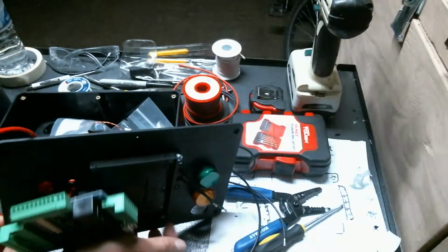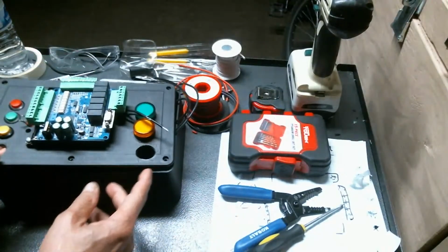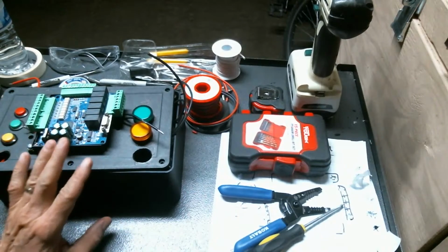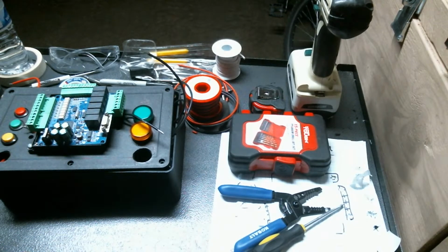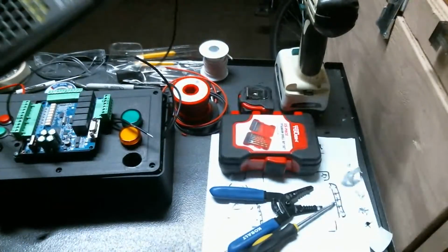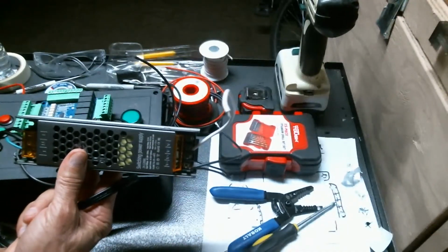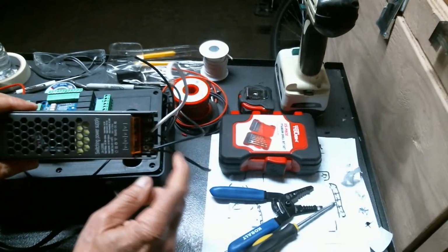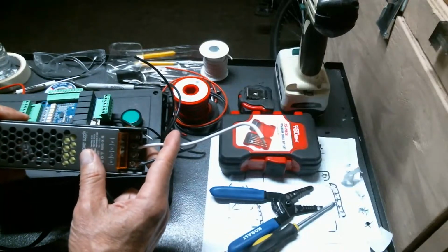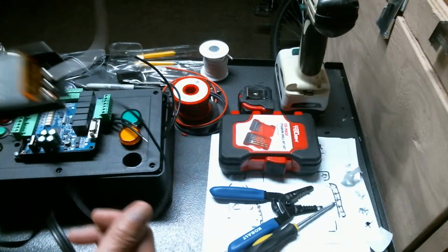You also are going to need a form of a power supply. These devices and controllers work with 24 VDC. Therefore, you are going to need a DC source, right? Like this one, this DC source takes 100 to 240 and outputs 24 at an amperage of approximately 0 to 3 amps. So this is the one I plan on using for this.